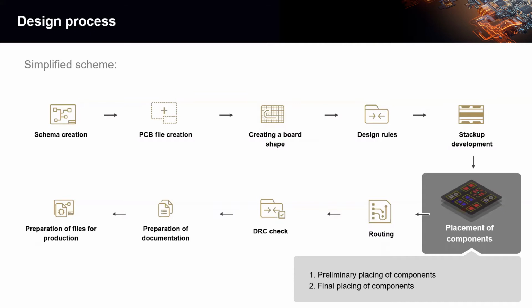And once you have that board shape and your stack up and some basic design rules defined, again, which is typically done in a PCB template project, then it's time to place your footprints, right? And that's what we're going to talk about today. And that's broken down into a couple different steps, some preliminary placing of components and then final placement as well, okay? Because sometimes it's more important to place some footprints more than others.